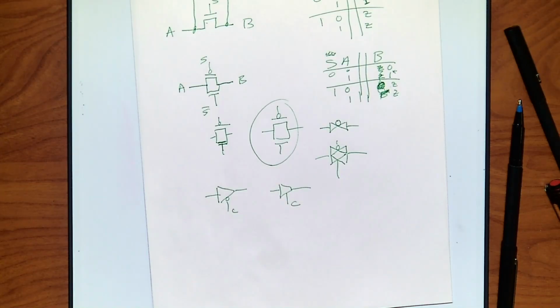If I hook that signal to one of these tri-state gates, I then connect my output signals to the bus. And if I'm not getting that signal, I'm disconnected from the bus. So in one gate structure, I've got a very nice way to connect to the bus, don't connect to the bus. That can be easily handled by a controller to identify when you're allowed to speak, and then I cannot mishandle this. It's an easy way to build that protocol. So, very nice way to handle buses. You'll see this a lot when you're interfacing computers. We do this type of thing.